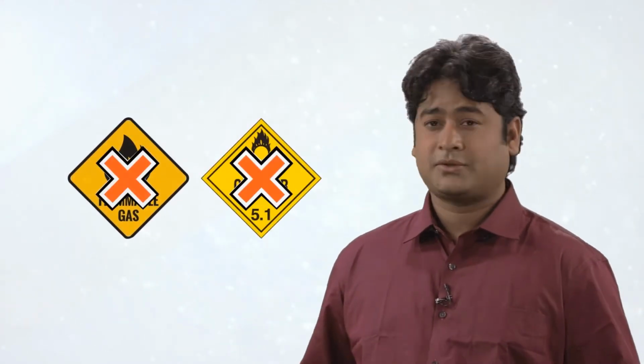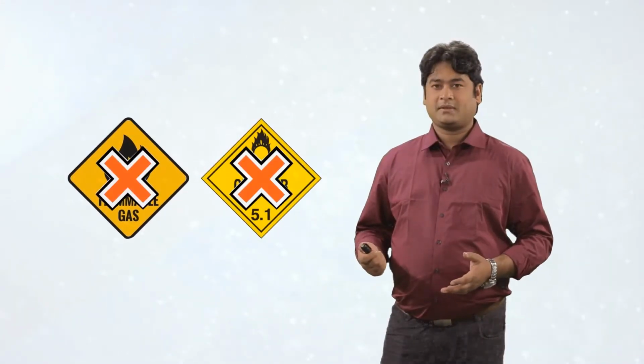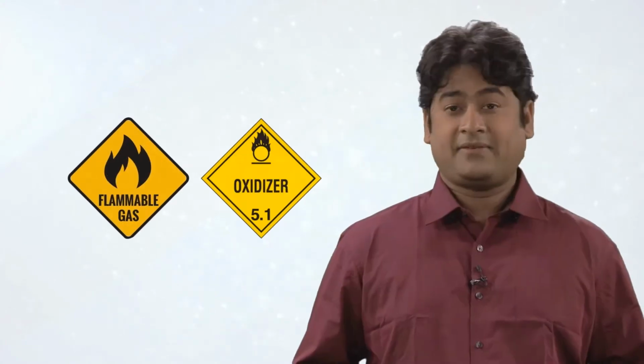Let us find out with another example what happens if we are not following this compatibility chart in our chemical storage. As you can see, this flammable chemical is not suitable to store with an oxidizer or with a toxic chemical. So, what will happen? If a flammable chemical is stored alone or with other flammable chemicals, and any fire or explosion occurs, it will only create a huge fume. But if it is stored with a toxic chemical, and afterwards any fire or explosion occurs, it will create a toxic fume, which is much riskier and may cause severe consequences.